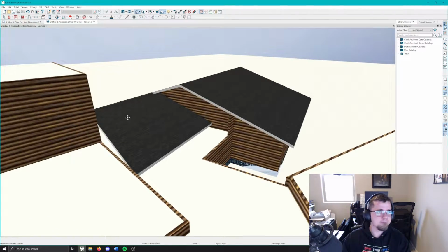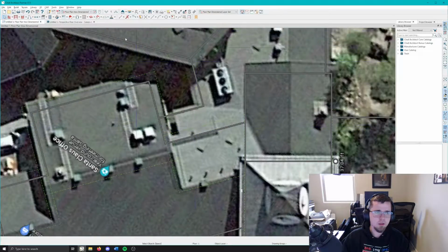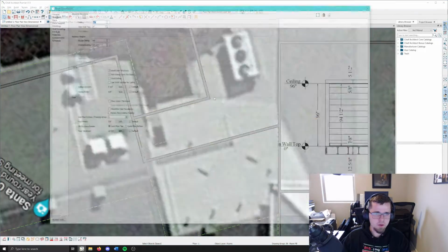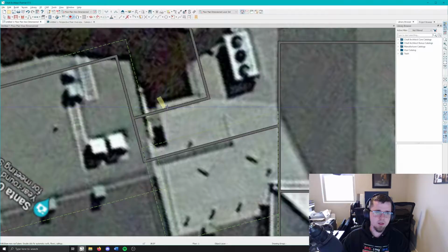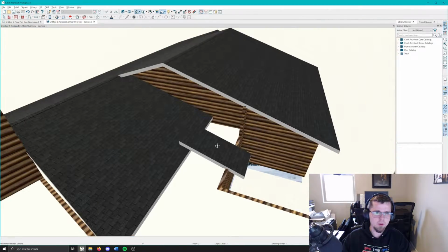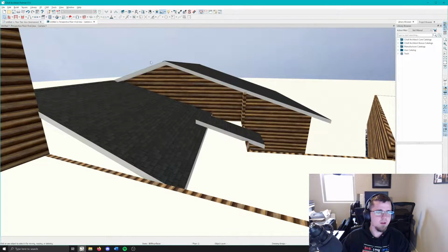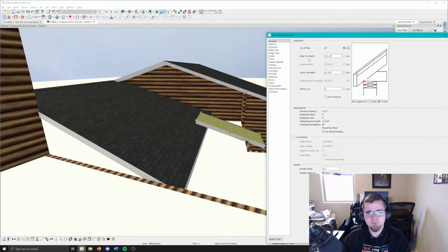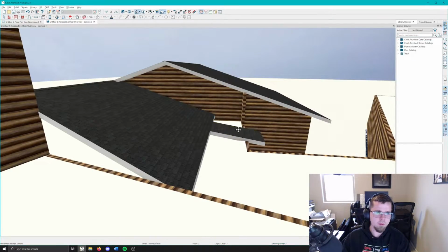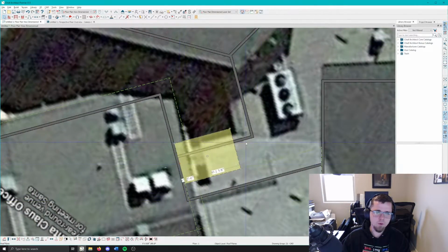Okay, let's make sure the plate here is still at the 10-foot mark that we had. Yep, 10 foot, perfect. So I'm gonna make sure this is still at 8 foot because it looked like it tried to draw it still at 10 foot. I'm gonna come in a little bit here. There we go, that'll probably fix it. Yeah, that's better. It still looks like it is a lower slope, but because I dropped that, yeah, you know what, let's do that. We're gonna lower this pitch down to like a 2/12, just to make this a little bit easier to draw out. Cool.